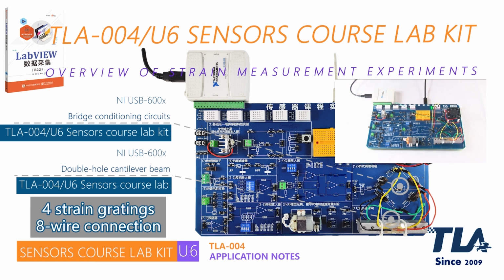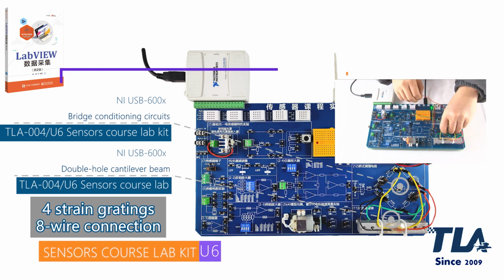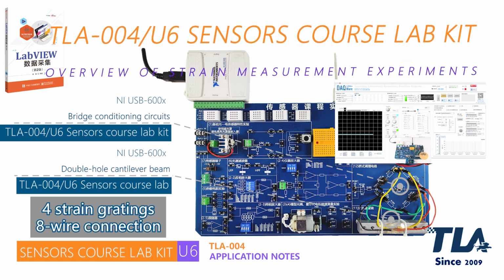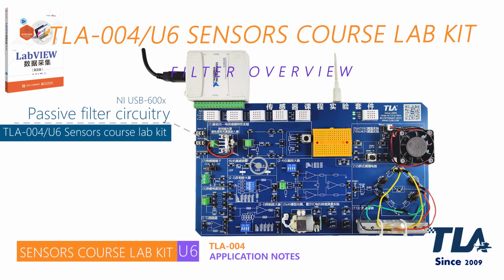This structure provides the same cantilever beam structure as the industrial weighing sensor, with 4 strain gauges of the same specification built in, and provides a complete 8-wire connection. It can be flexibly combined with the bridge structure in the experiment to meet the needs of various strain measurement experiments. The kit also provides weighing weights, and combined with the experimental software DAQ, the verification of experimental measurement data of metal foil strain gauge characteristics is completely realized.